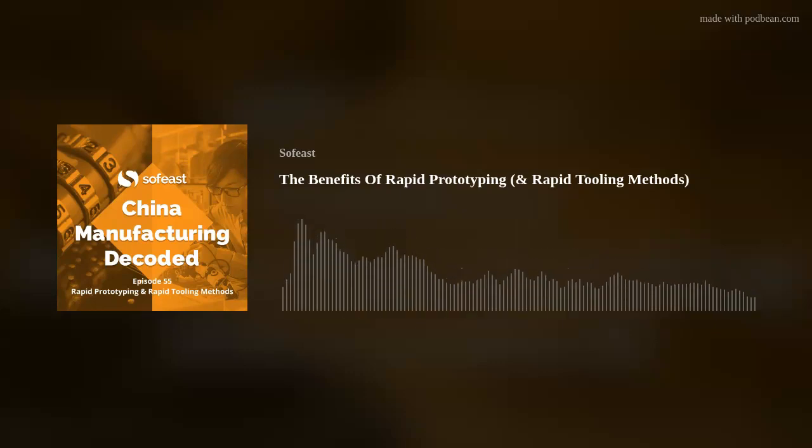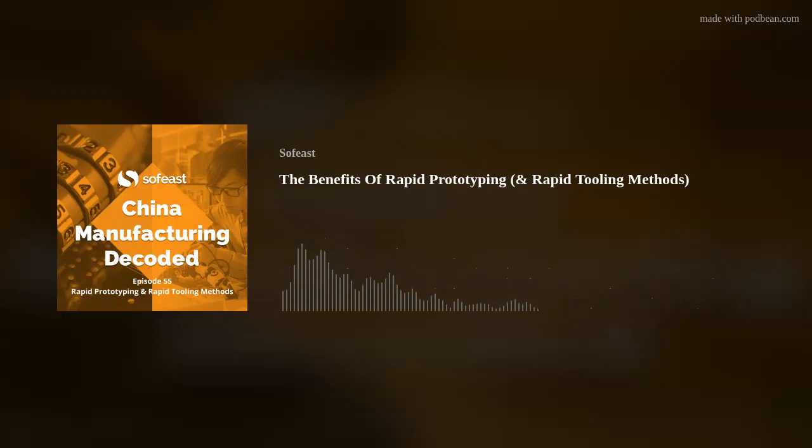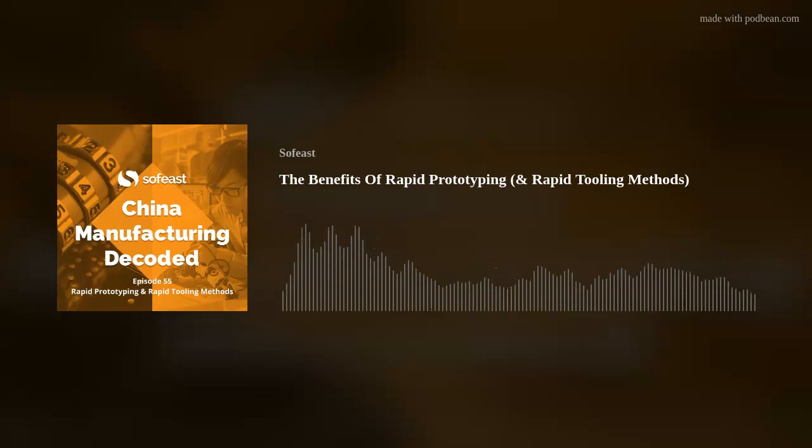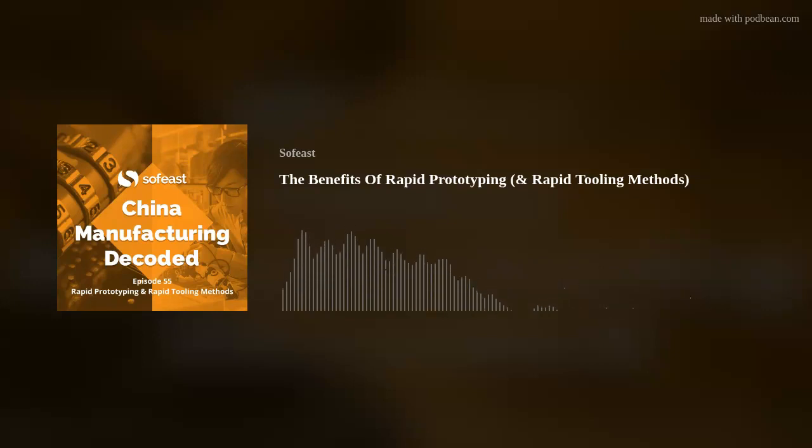So that's fine. This is going to be used for mass production. It depends on the grade of steel of the tooling, but also on different factors. Some plastic polymers will get the mold used up, basically going to end of life much faster, right? And also certain geometries of the parts will have an impact, right? So the key is whatever is going to be used in mass production, basically.